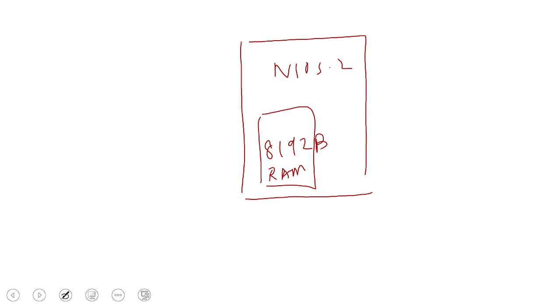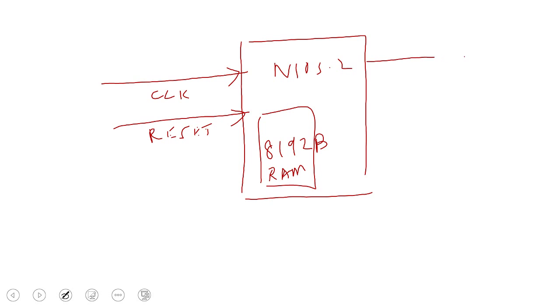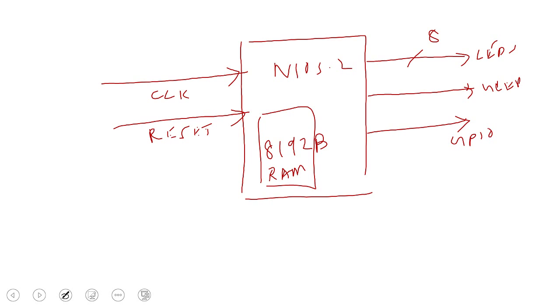and we were asked to connect a clock, a reset, and then we were asked to connect 8 LEDs at the output, and then a single green LED, and two GPIO pins, one as an output from the Nios processor, one of the output devices, and there is another GPIO pin somewhere outside for some reason. And we were asked to connect a push button,